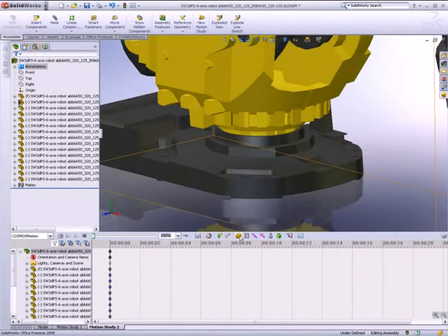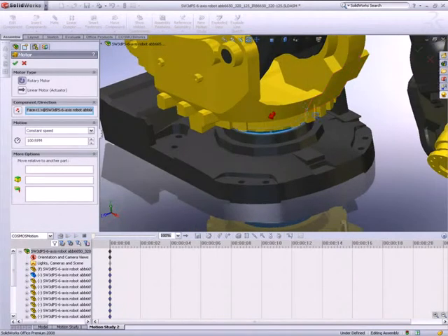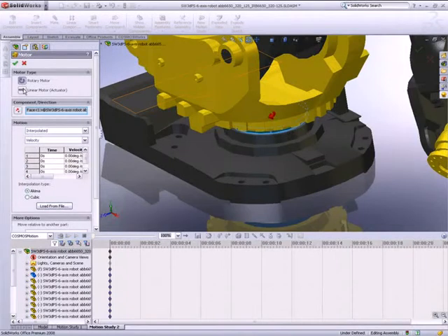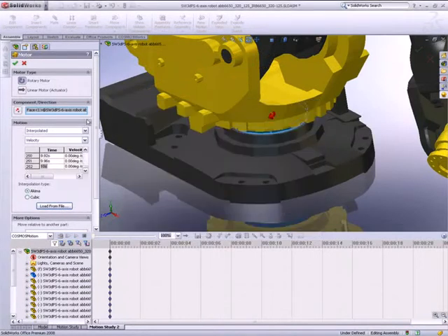With the various motor actuator functions available in SolidWorks Motion, you can move any assembly component with a particular motion profile. All motion objects are accessible through the Motion Manager toolbar. You can apply a motor with the following profiles. Constant speed. The motor speed is constant. Distance. The motor operates for a set distance and time frame. Oscillating. You can enter the values for the amplitude and frequency. Interpolated. You can load the values from an interpolated function. Expression. You have more complex result-oriented functions.